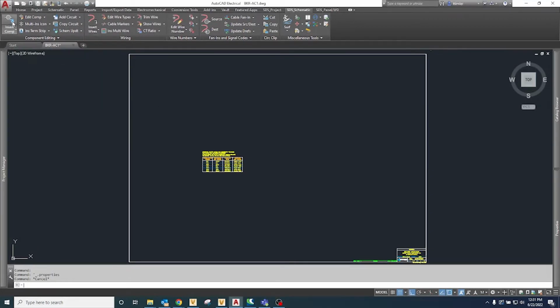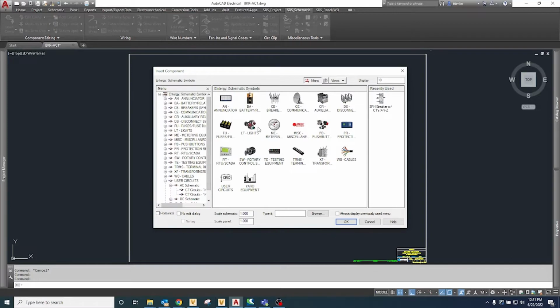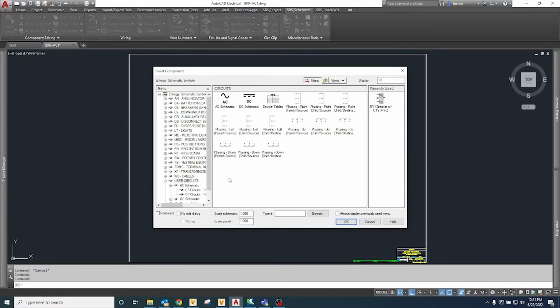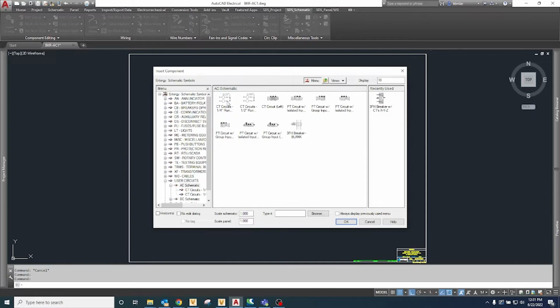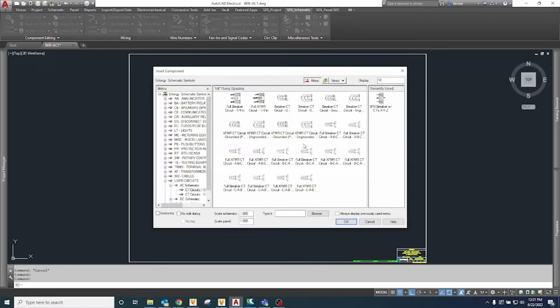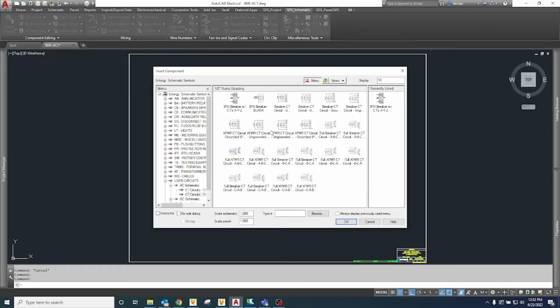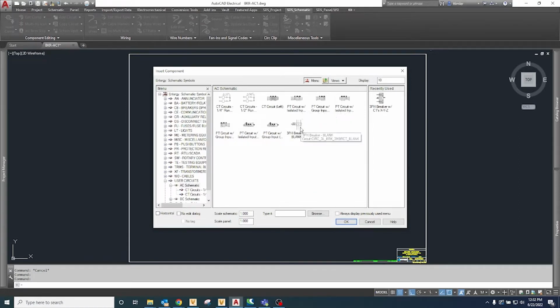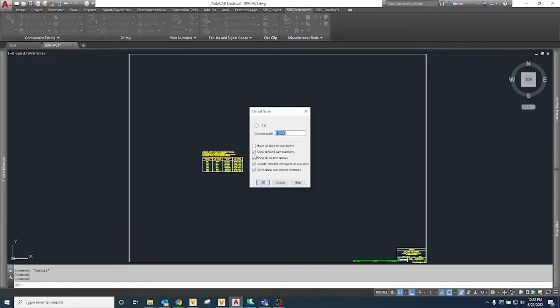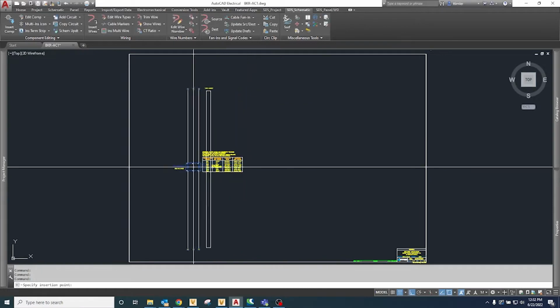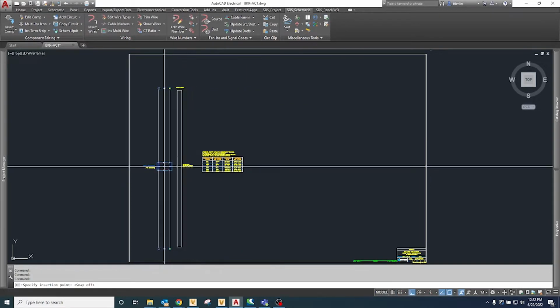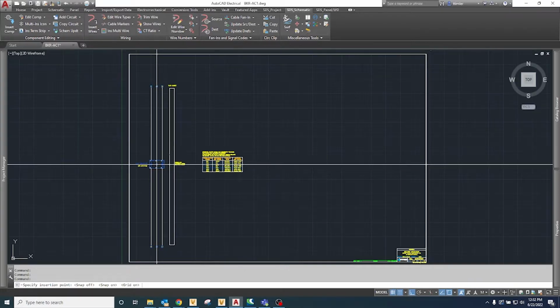In this AC drawing, I've already inserted the CT tap chart for my first breaker, so now I'll continue to insert the breaker components. Instead of inserting symbols one at a time, I'm going to use circuits. Under User Circuits, AC, I have a variety of 1/4 inch and 1/2 inch spacing options for grounded and ungrounded bushing CTs. Those come with cables or without cables, and also come with full bushing CT circuits that have cables and control panel equipment. I'll start with a blank 3-phase breaker circuit template, turn on my grid snap, and go about placing the circuit.